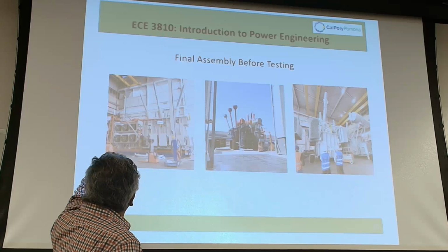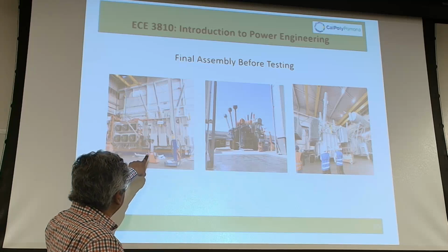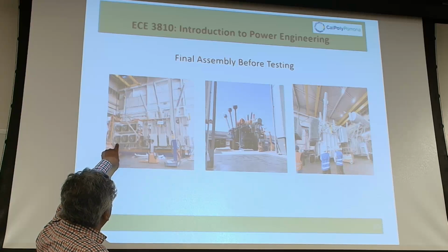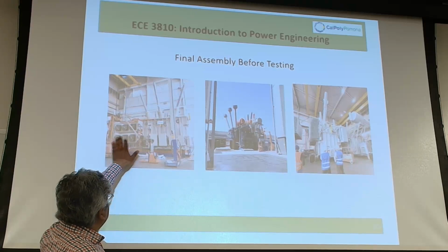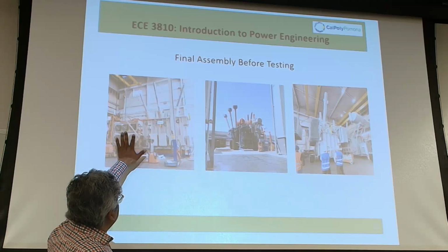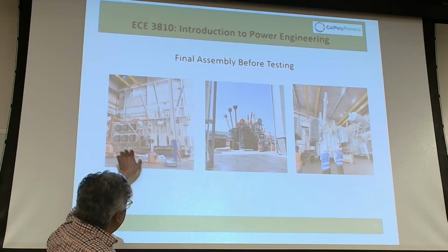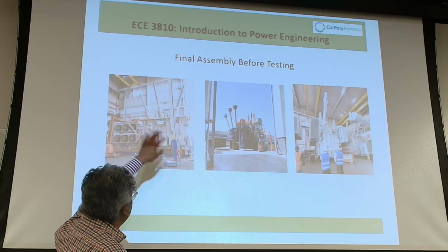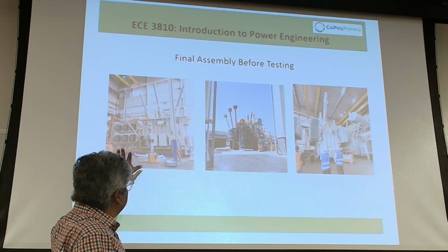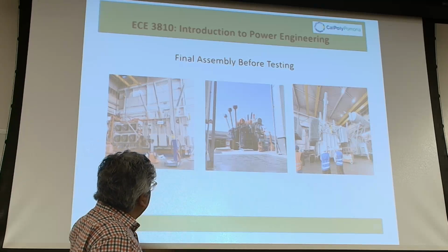This one was a 150 MVA. Actually, it was for the US, one of the utilities in the East, I cannot remember which. And you can see this one has the radiators separate. The reason is that right here they're just testing the transformer, so they're not there yet with the full assembly. They're starting to put in oil and flow the oil. They don't energize it, but they also want to test the controls for those fans. They're separated, but eventually they will bring it through here.